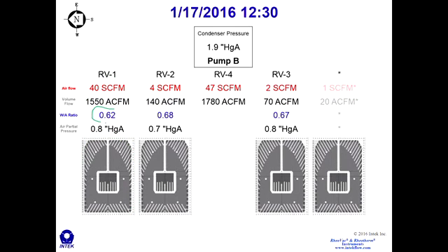What else we can tell is that the water-to-air mass ratio is very low. We'll see in a few minutes that if this value is below 3, then we know there is excess back pressure in the condenser. And so with these measurements, the client was confident that air and leakage was coming in somewhere in this north wall of the condenser, going through this bundle, leaving this air removal section, and so they were able to narrow their search for air and leakage.